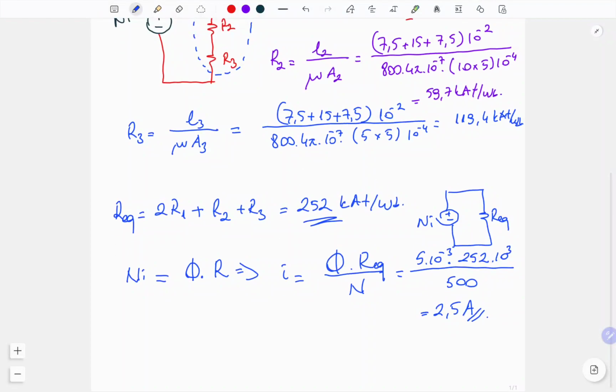Okay, so in addition to current and flux calculations, we can calculate the magnetic flux density for such a system. How? The magnetic flux density and flux relation can be used. B is equal to phi over A. So what do we want to calculate? For the density, instead of a single flux rotation inside the magnetic core, our cross-sectional areas will be important. So if we have different cross-sectional areas in different parts of the core, the magnetic flux densities, because of the density term, must be different.